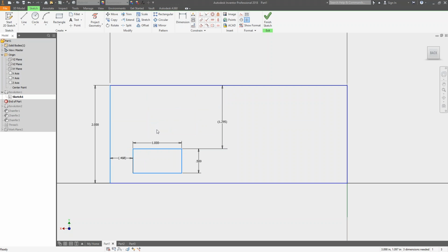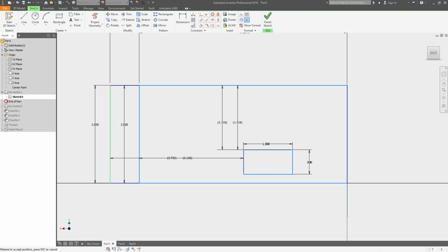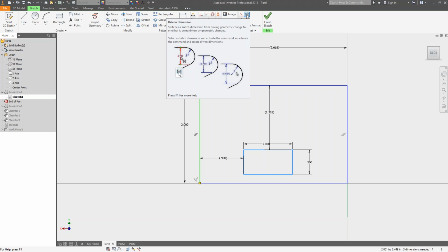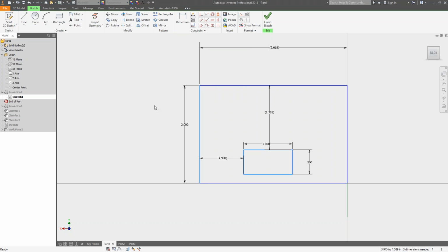And the cool thing it does is it shows you the dimensional value that it equals. So you can see, okay, that's close to 1/2 inch, that's close to 1.25. So maybe I make that the actual number. So it gives you some flexibility when you are working with your geometry. So driven dimension, lots and lots of benefit using those. So yeah, it's right there. It should be one of the last commands you have in the upper right-hand corner. Interesting. A couple other things, Luke.